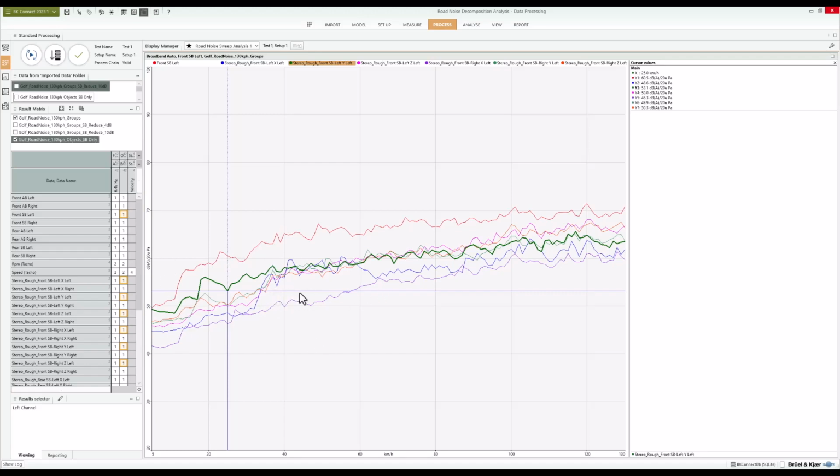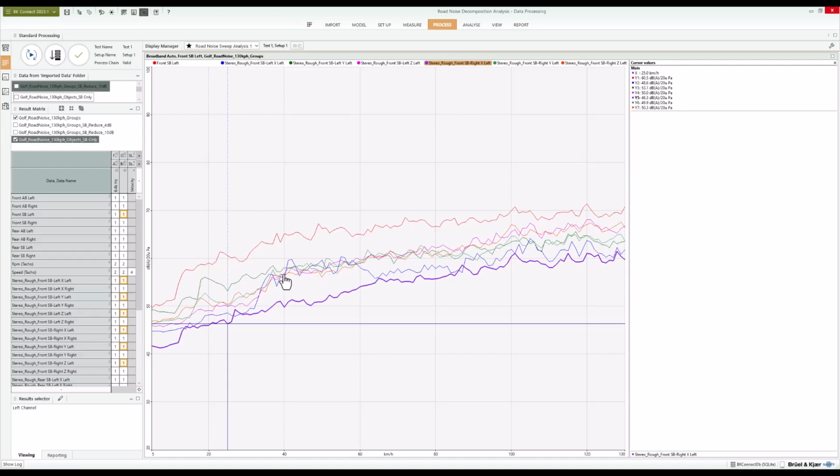So we go to the mid-speed range. We've got a couple lower contributions, but most of them are pretty consistent across the range. The lower ones are front left X and front right X. So that's our longitudinal directions. Those don't seem to be quite as important in this speed range. So really, if we're looking to drop the overall level in the mid-speed range, we'll have to focus on the great majority of these sources. So we've learned that maybe a bit more study is required there.